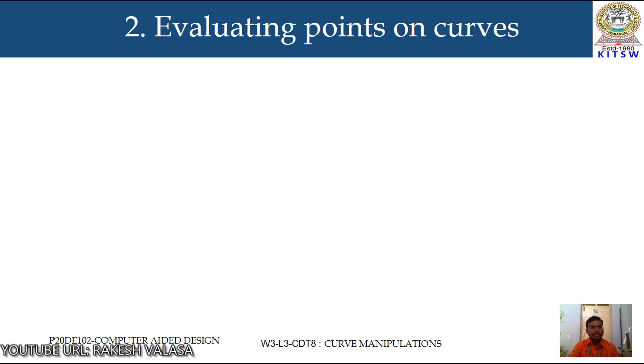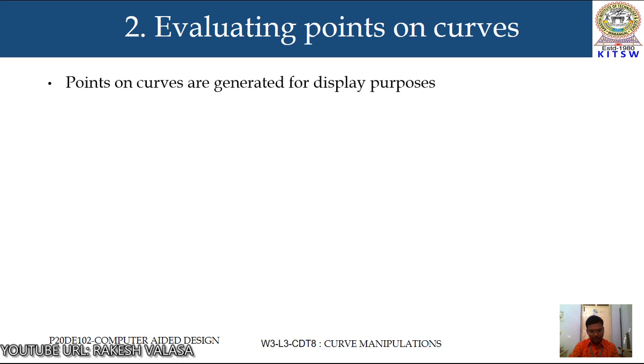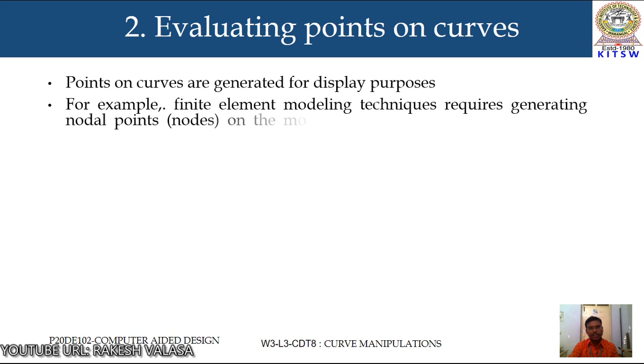The second one is evaluating points on curves. Points on curves are generated for display purposes, as already discussed in the previous slide. For example, finite element modeling techniques require generating nodal points on the model to be used later in finite element analysis.